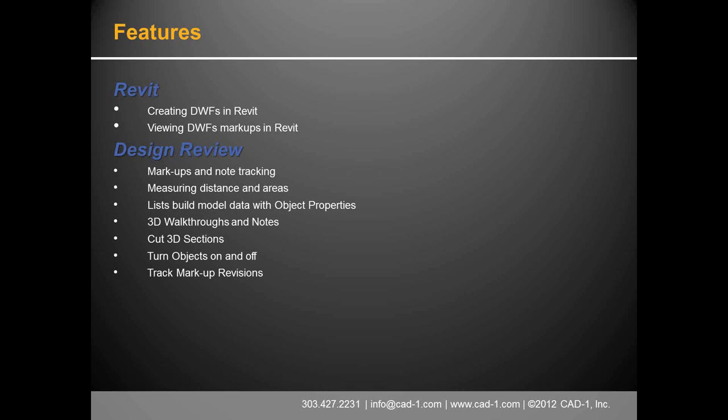If you have Windows Explorer, you can actually open up a DWF file in Windows Explorer and play with it in there. You won't have all the markup tools. You'll have some very standard markups in there. You might not be able to do everything, but you don't necessarily need Design Review to do it. Now, Design Review does give you more for it. You have more tools and options available to you, and it's free. It's like 300 kilobytes. It's a pretty darn small file to email to someone or just to give them the link on where it's going over.